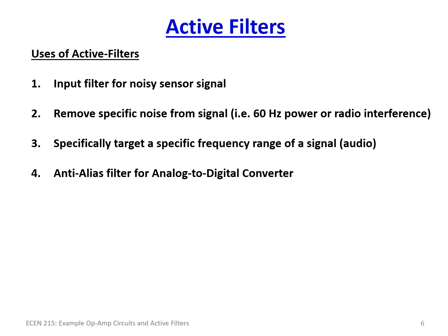Because if you do that, you'll end up with something called an alias. An alias is basically a figment of the fact that you are sampling too slow. You actually see this every time you watch a movie, or even as you're watching vehicles drive down the road and it looks like the wheels are going backwards. That is because of a thing called aliasing. Your eye is actually sampling the visual activity that you're seeing slower than it is actually rotating.